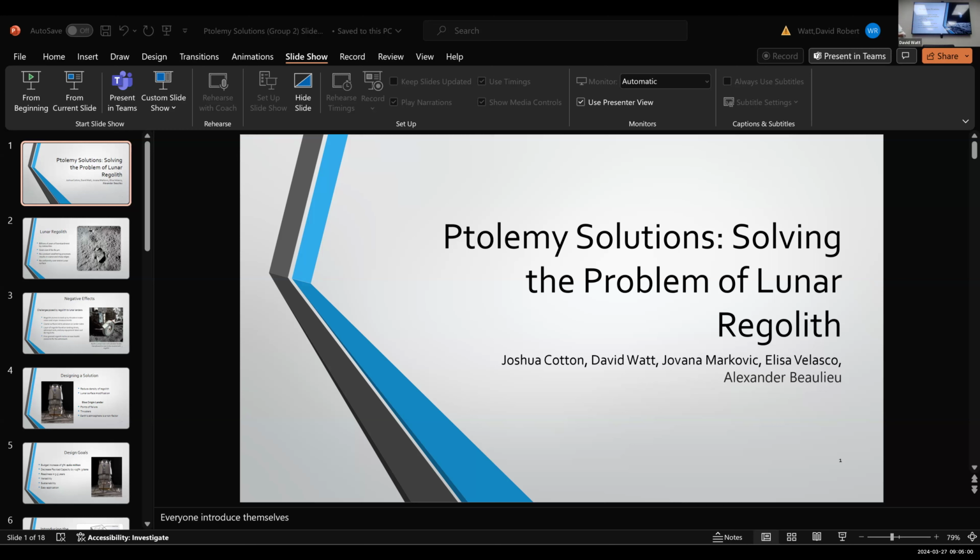however, the tarps overlay the ground. They overlap each other, so you're not going to get two tarps where you have a coverage of 20. With the overlap included, on the surface of the moon it's going to be 16.2 by 10.6 meters. We assumed that the lander is roughly 5 meters in diameter, so that is ample coverage for the lander. And like David mentioned in the previous slide, it should, with a rough estimate, reduce the contact with regolith by about 49-50%.